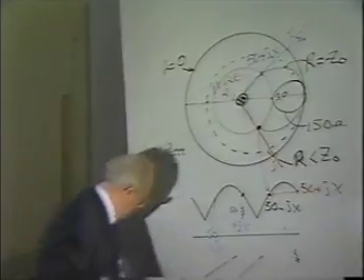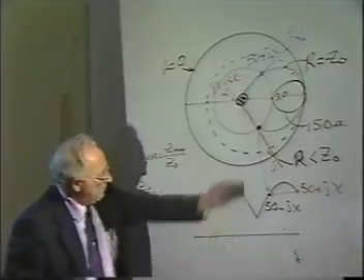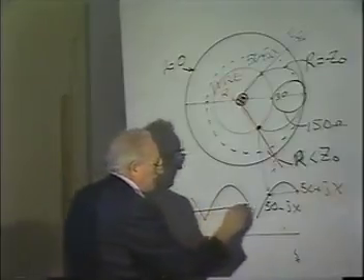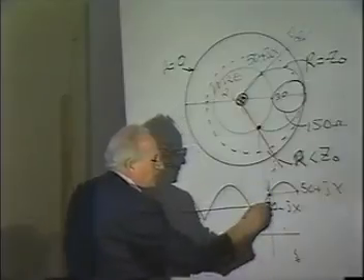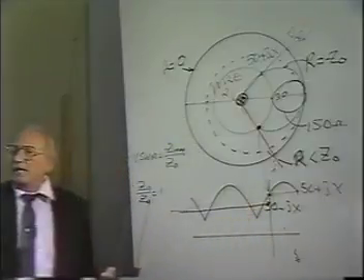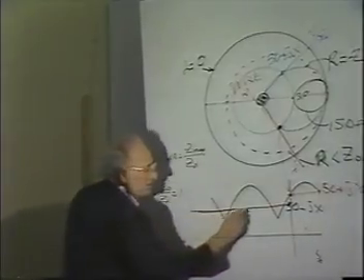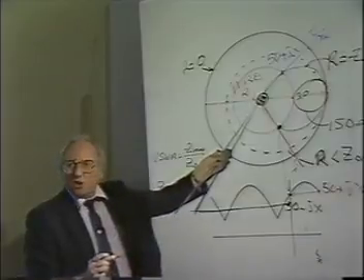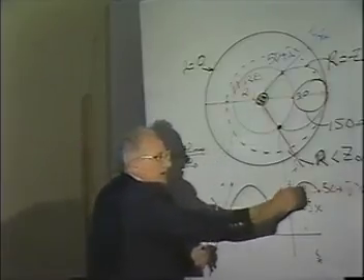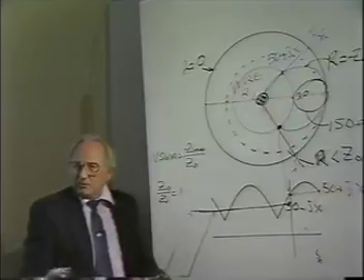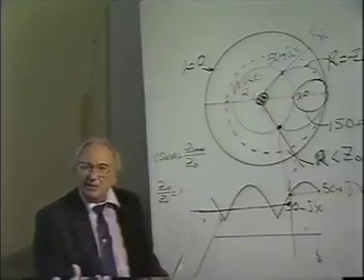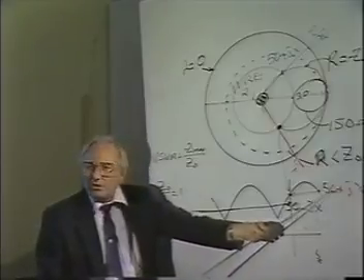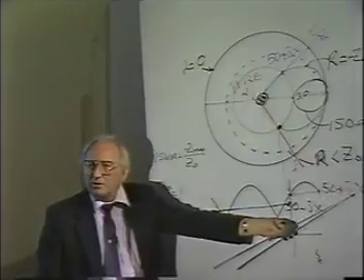What would this look like on the transmission line now? What would I see if I put the JX in? I would see no standing wave, right? I would see this. No standing wave, because I've moved back to the center of the chart. You still have the standing wave pattern in here, don't you? It is a little different than the way it looks there because it's been redistributed so that all the power that goes past this point is dissipated in this 50 ohms resistor here, regardless of what this is.